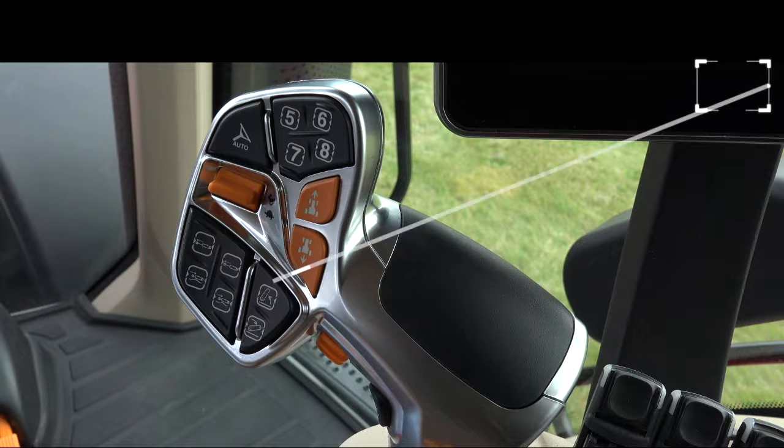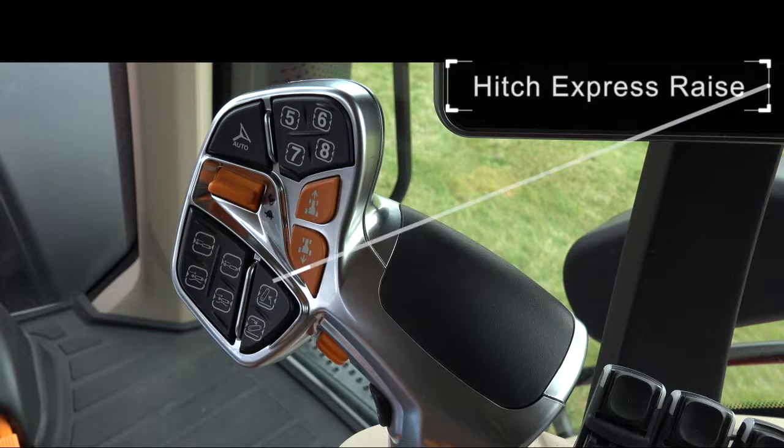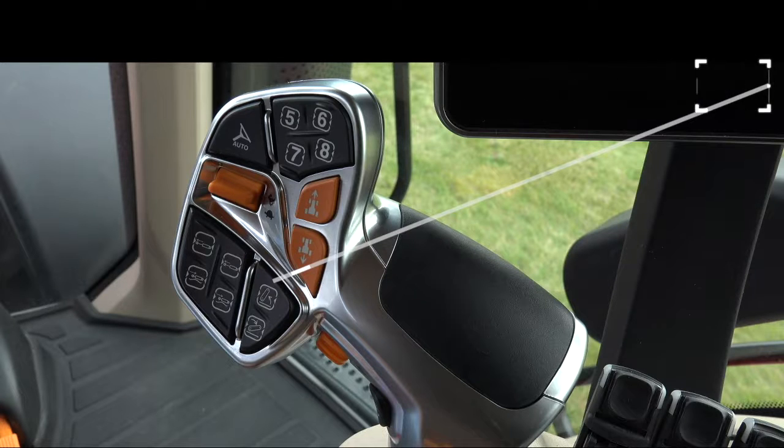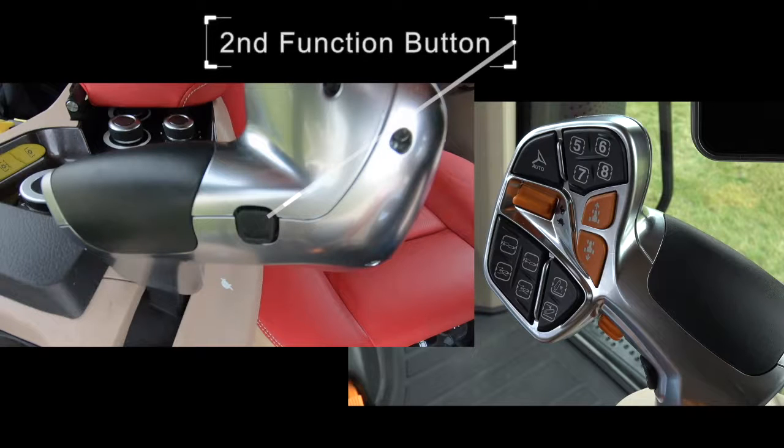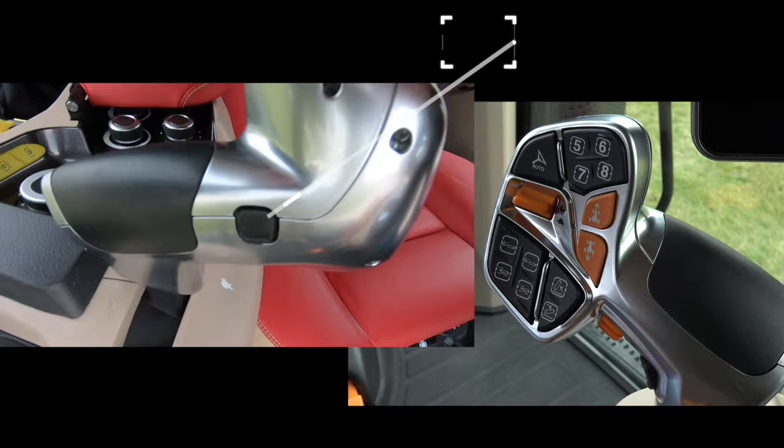Hitch express raise. Raises the hitch from its working position to its upper limit setting. Holding the second function button on the back of the multifunction handle at the same time will command the front hitch, if equipped, to raise to its upper limit setting.